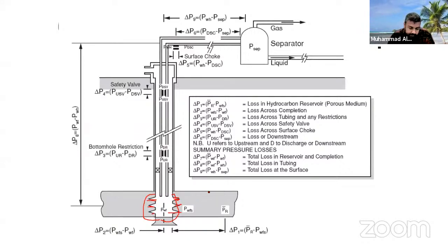If the oil is flowing and is stuck here, restricted here, there is definitely a pressure loss. And once this oil comes inside the perforation and tries to go inside the tubing, which as I said is only probably 2.5 inch from here to here, this size, it is a very small size, and again there's a pressure loss. And then you have the restrictions. As I said, we have a safety valve, we have a gas lift valve, we might have installed any other equipment. So there could be further diameter restrictions here, which can reduce the production rates.